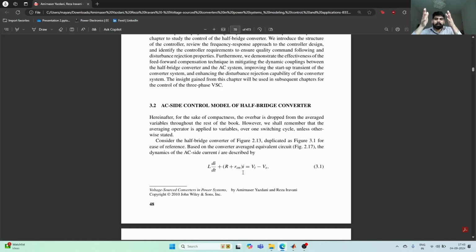Maybe I will have a particular set of values of m, where I will have a particular set of currents in the output. Let's say for m equals 0.68, I was getting 1000 amps, and for 0.685 I was getting 1500 amps. For m equals 0.70, I will get, let's say, 2000 amps. But I don't want that kind of manual control, or what we call a fixed value. What I want is to just give an I reference, that this is the amount of current I want to be delivered, and you do it. The controller would do it for you.